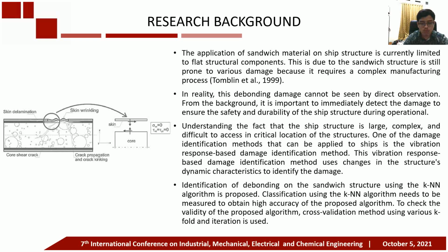Understanding that the ship structure is large, complex, and difficult to access in critical locations, one of the damage identification methods that can be applied to ships is the vibration-based damage identification method. This vibration response-based method uses changes in structural dynamic characteristics to identify the damage. Identification of debonding on the sandwich structure using the KNN algorithm is proposed. Classification using the KNN algorithm needs to be evaluated to obtain high accuracy. To check the validity of the proposed algorithm, in this case the cross-validation method using various K-fold values and iterations is used.